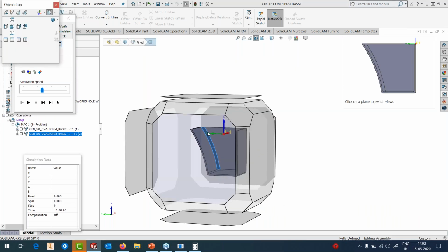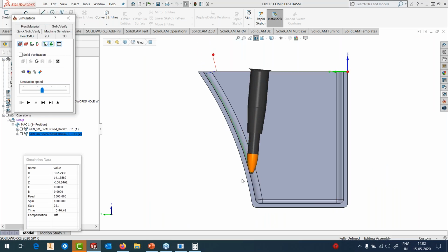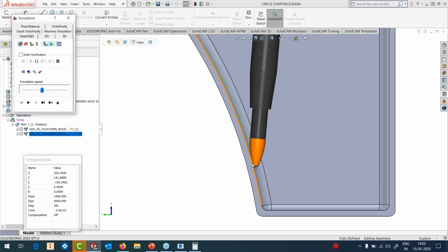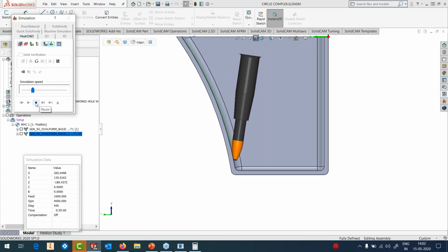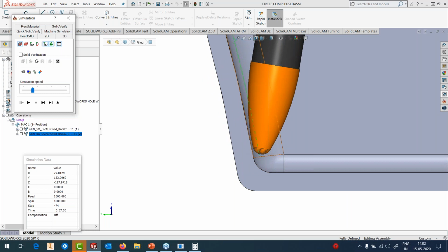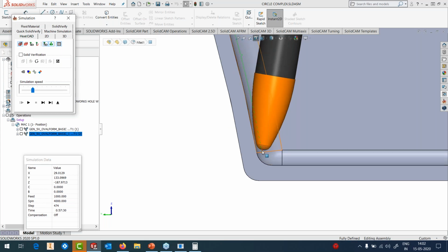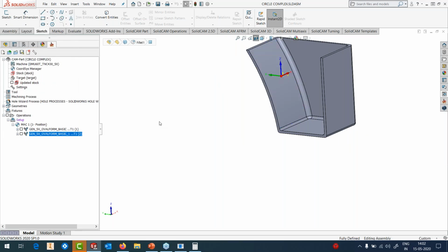So we support all the 4 tools. Our 5th tool support, you can see as it goes down, the contact is changing, so is my tilt angle. I have not defined any angle here. And once it goes to the end, you'll see that it stopped here. So it's not 20%, it probably could be 25% or 28%. Because it would have created a collision with the fillet here, it stopped and retracts up beyond what is allowed, okay? So you can use these tools, reduce your machining time, machine almost any kind of geometry, apart from the ones that I just said, they are big challenges for us.